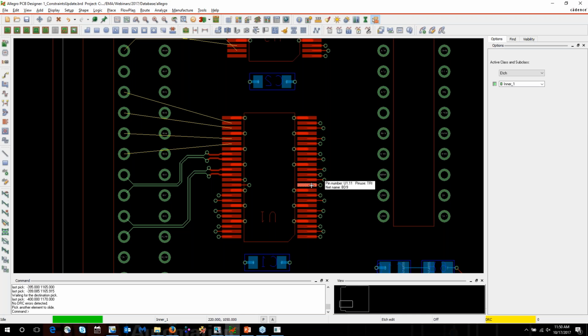Okay. Got another great question here. Will this work with Allegro PCB Editor, or is it just for OrCAD? It works with both Allegro PCB Editor and OrCAD PCB Editor. Okay. And another one, what if we outsource layout? Can we still use this to define constraints? Yes, if they're using PCB Editor, either Allegro or OrCAD PCB Editor on the back end, you can still add your constraints here. They'll be able to see them when they open up the .brd file.